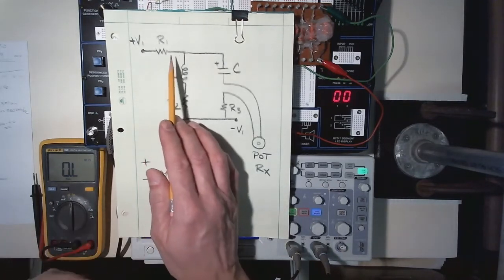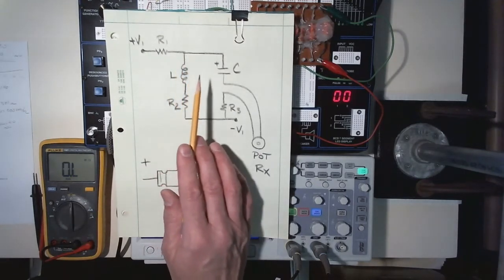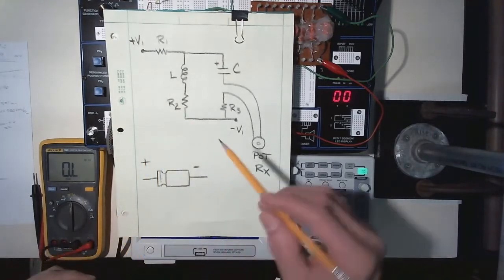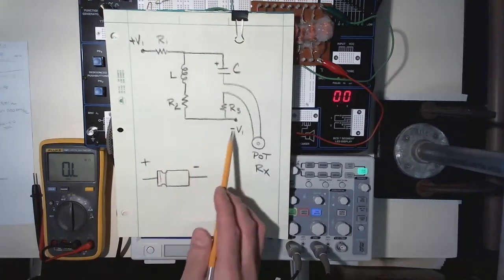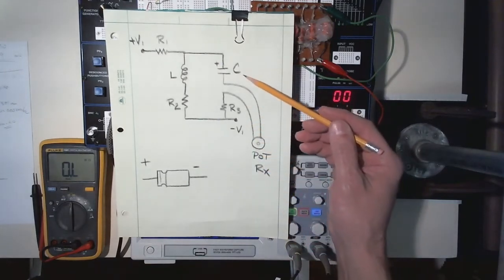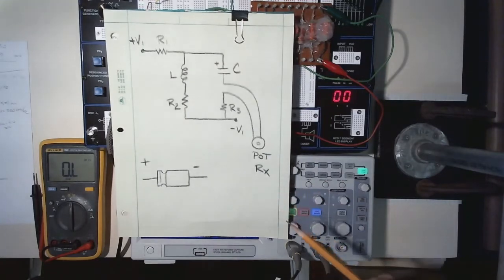This resistor up here is supposed to be, let me double check my notes here, 1 k ohm. We'll measure it and get that exact value. And like I said, that's really just for protection. We're more interested in this portion right there. Then the capacitor, we're just going to take it at its face value of 25 microfarads, although I believe it's plus or minus 20%, so that could vary quite a bit.